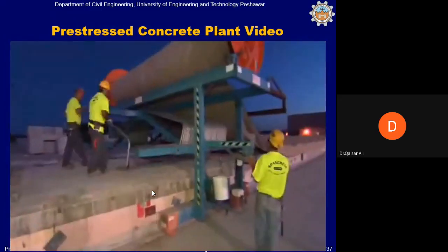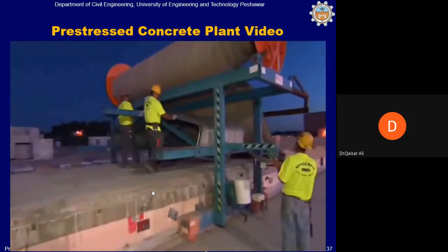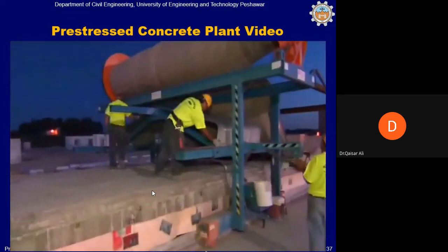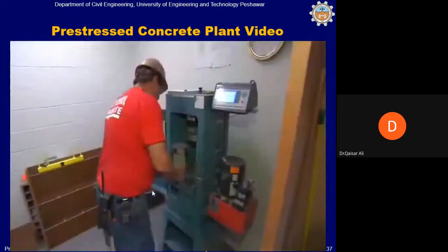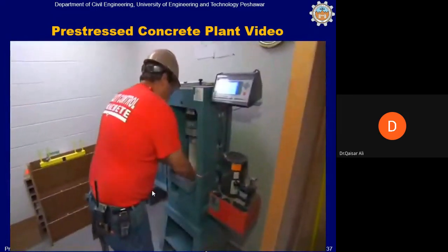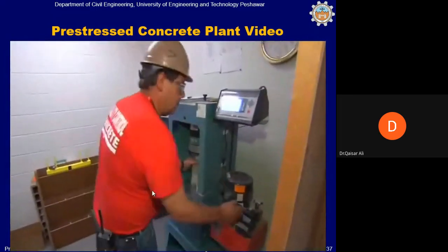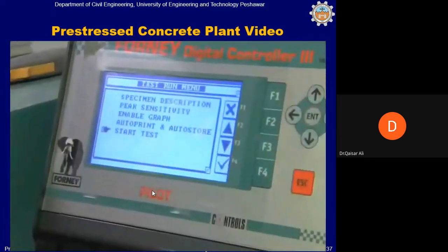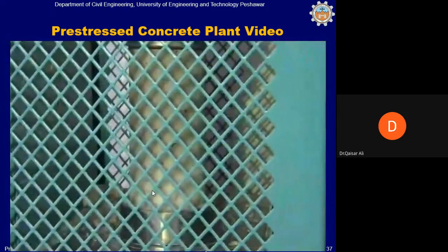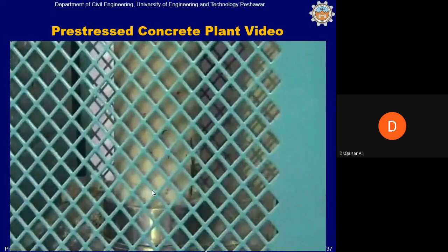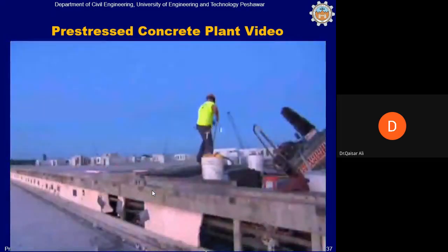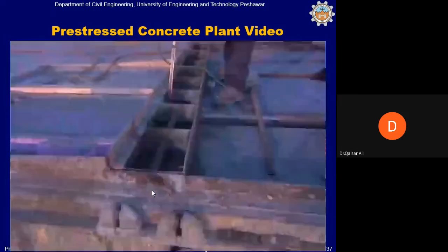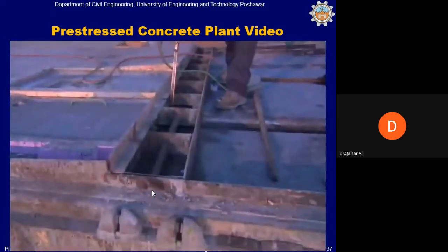After 12 to 16 hours of curing, the tees are ready to be stripped. The QC department first tests the concrete to be sure it has achieved the strength required to detension the strands, typically 3,500 psi. This is a typical test being conducted. The strands are detensioned in a specific sequence established by the QC department or the plant engineer.